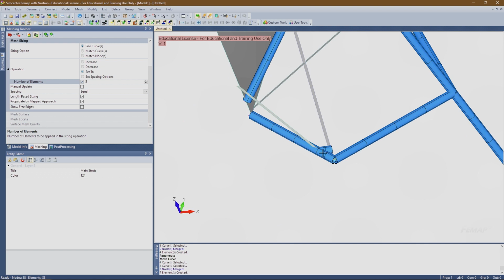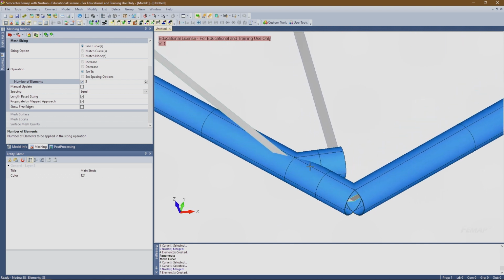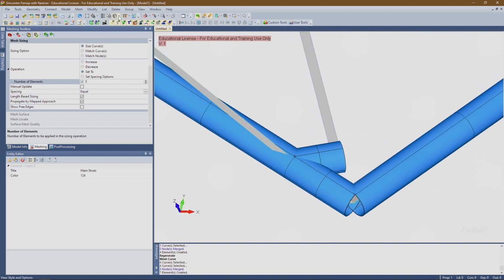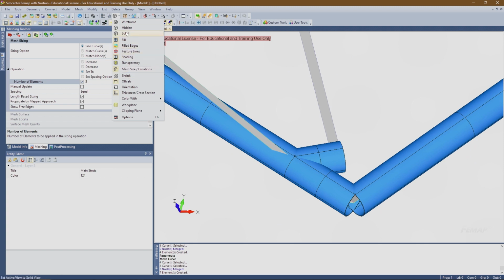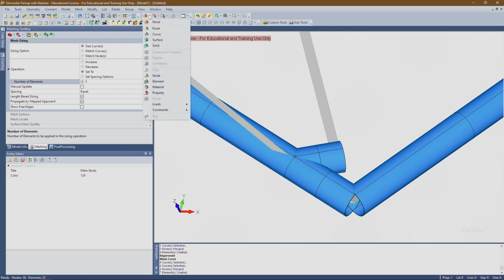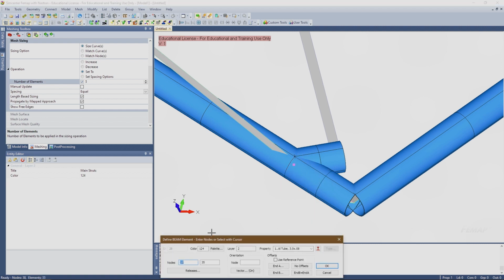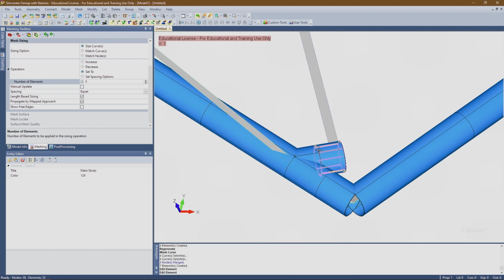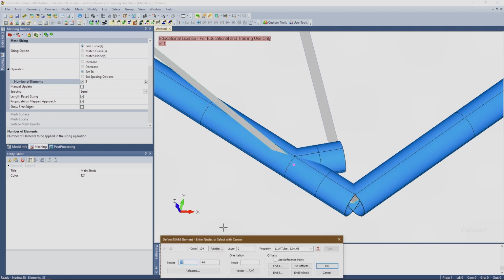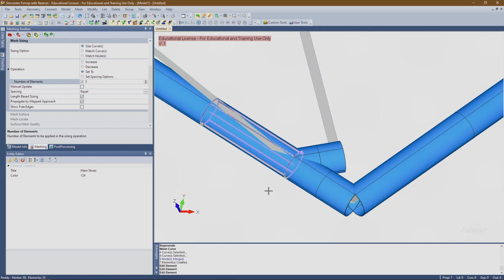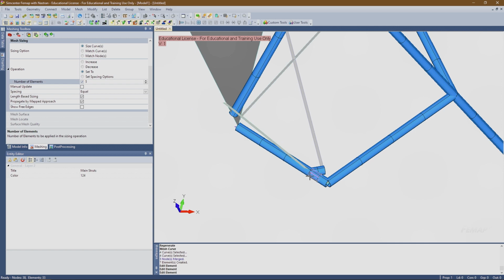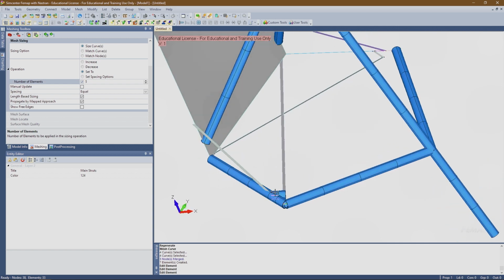So that's another strut. And just to check, there's like a confluence here of 3 elements. So if we go to our selection filter, change it to element, edit, 37 and 35 are the 2 nodes this is using. 37 and 40, so 37 is the common node, and then 37 and 44. So you can see all 3 of these elements right here share the same node, which is what we want, which means that they're connected.